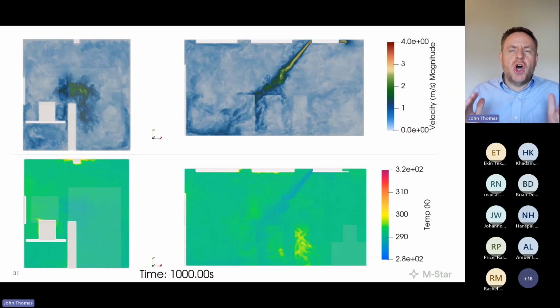A simulation is hard, quote unquote, when you have a 1 millisecond time step that's being advanced for an hour, and you then have to do 1 million plus time steps. A simulation is hard when you have high spatial disparities, say small features, say a caster of a wheel on a chair inside a 10-meter diameter room. Simulations are hard when the aspect ratios are great, but that's precisely where tools like this shine.